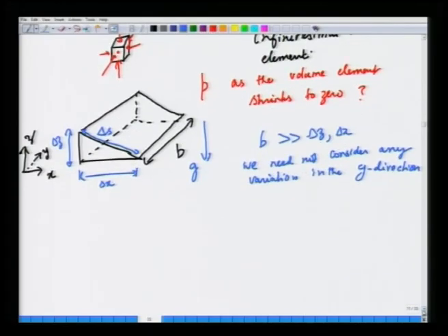Okay. So, now first we will ask what are the various forces in order to prove that pressure is the same. Let us give some notation. Let us call this P z. This is the pressure that is acting on a surface whose perpendicular is in the z direction. Let us call this P x. This is the pressure acting on a surface whose unit normal is in the x direction, and let us call the pressure on the inclined surface P n. Let us call this angle theta. This is also angle theta by geometry.